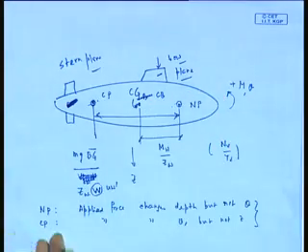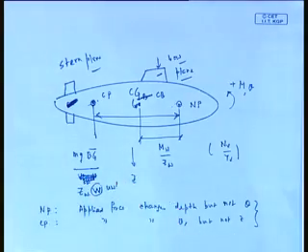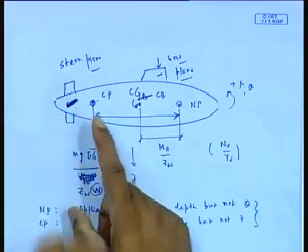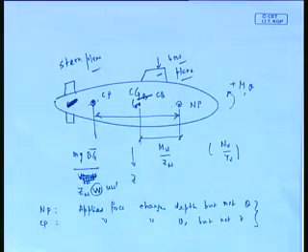In the horizontal plane maneuver, there is nothing like a reversal. If I turn the rudder to the opposite side, a stable ship will go in the opposite direction. It's not that at 10 knots it goes starboard with starboard rudder, and at 2 knots it goes port. It will never happen. But in a submarine we find it happening for the stern plane. Remember, the rudder is like a stern plane at the aft end of the hull. What is the difference?